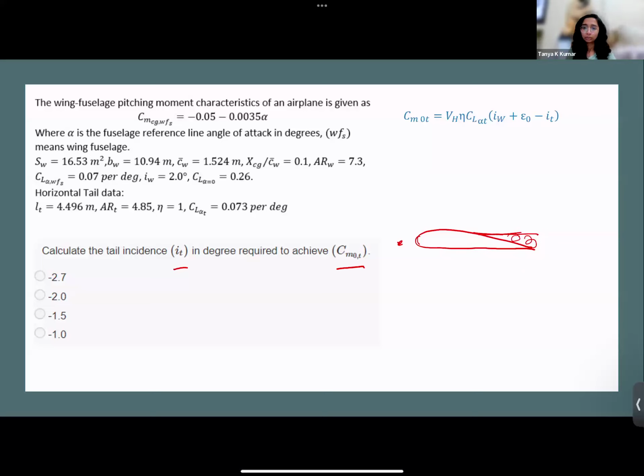So this is one of the ways in which leading edge vortices are encountered. Another case that I'd seen was when there's a highly swept back wing. Even in this case, changes in angle of attack lead to quicker boundary layer separation at the leading edge. All right, so these are some of the conditions I saw where leading edge vortices are created. Do let me know if you find other such situations, but this is what I was able to find out.